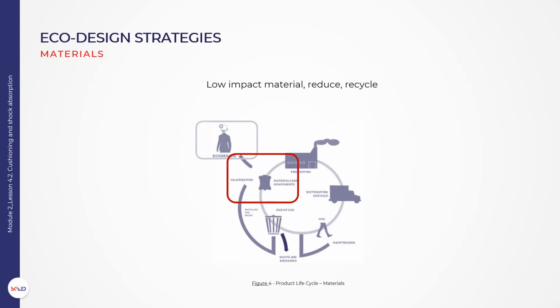There are multiple eco-design strategies regarding the materials including 1. Select low-impact material, namely renewable materials, recycled and or recyclable materials, biodegradable materials or materials that involve less energy consumption. 2. Reduce the use of materials, for example reduce the weight, reduce the volume and reduce the variety of materials in the same product. 3. Avoid potentially hazardous substances and materials by acting proactively and analyzing documents to check human health and safety, environmental aspects and impact of materials during their life cycle including in transportation.